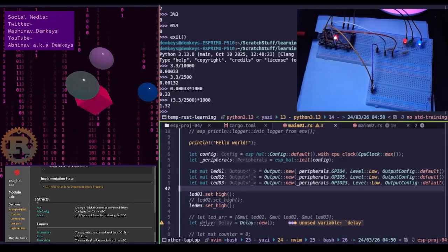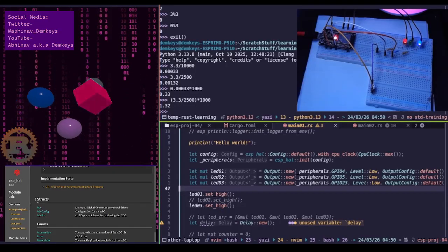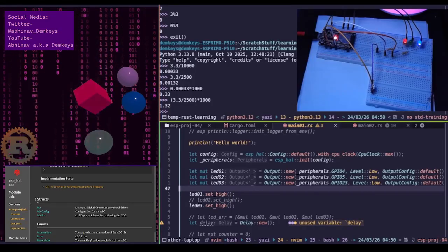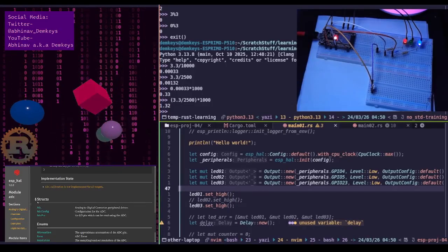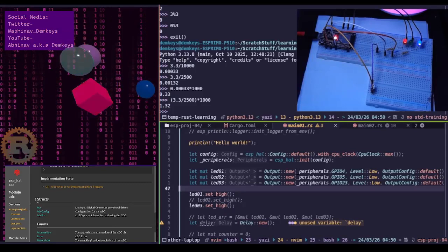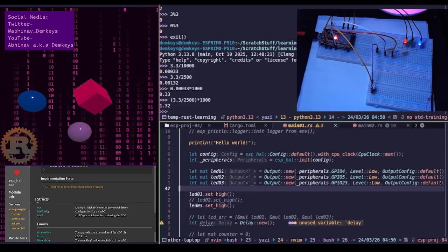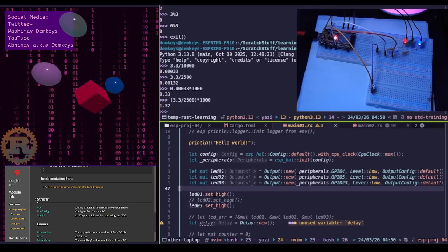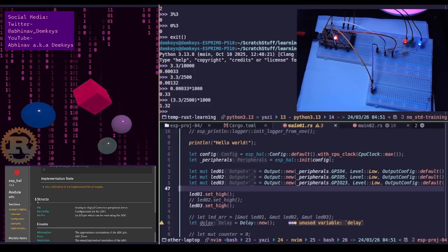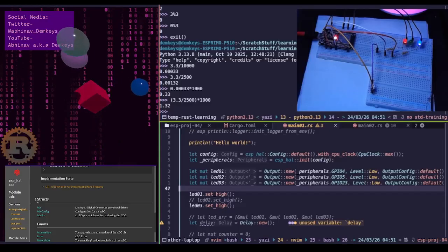The resistance buffer. If you took a plain wire and connected 3.3 volts directly to ground, the resistance would be almost zero. And according to I equals V divided by R, if R is nearly zero, the current becomes massive, and that is a short circuit: heat, sparks, and a dead ESP32. Okay?